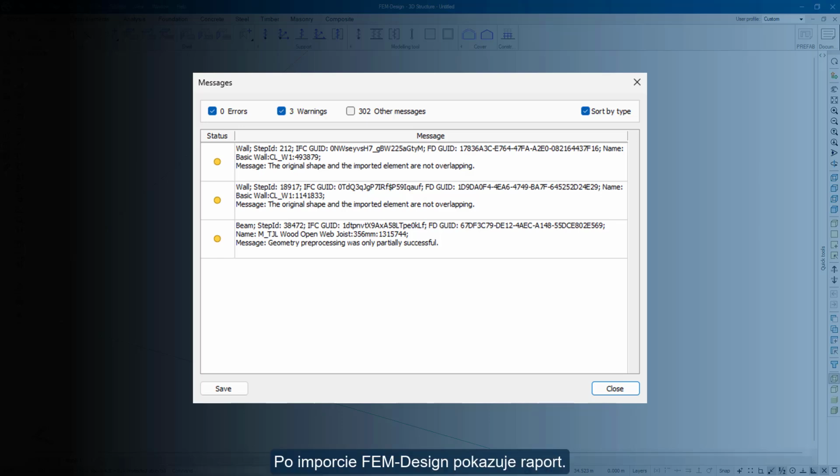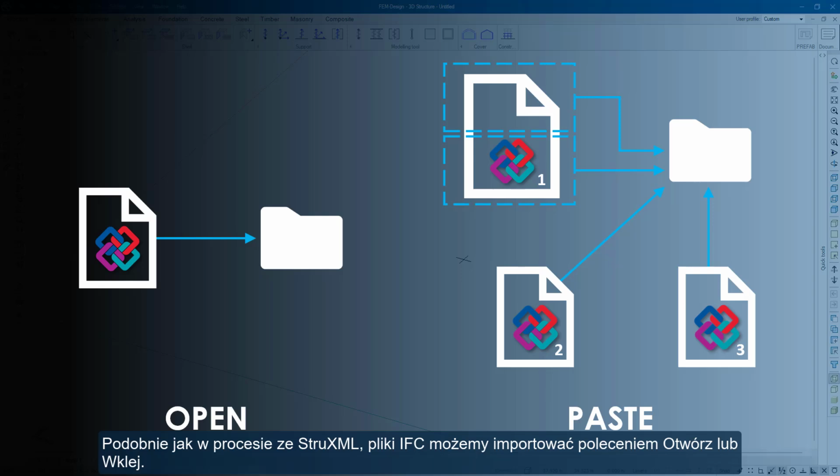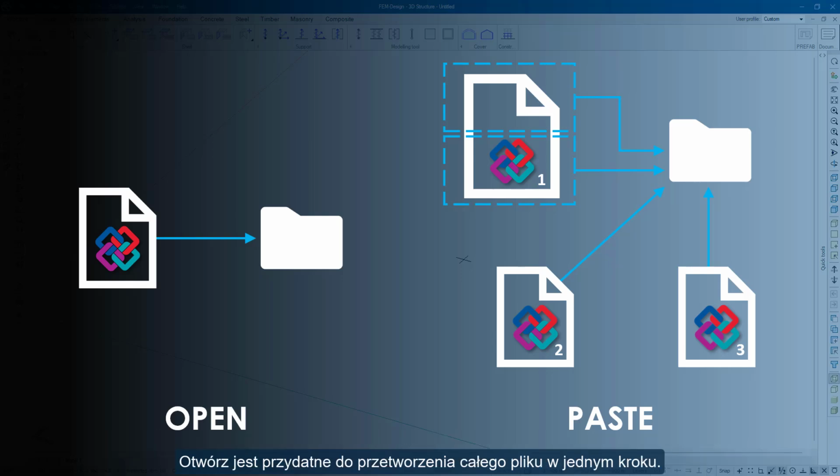After import, FEM-Design shows a report. It may include warnings, for example, about geometry simplification. Similarly to StruXML workflow, we can import IFC files with open or paste. Open is useful for processing the full file in one step. Paste gives more control when we import by story, by layer, by element type, or from several IFC files.